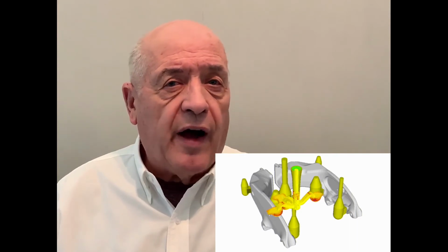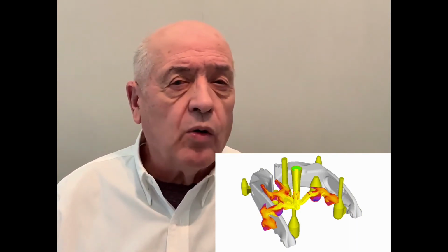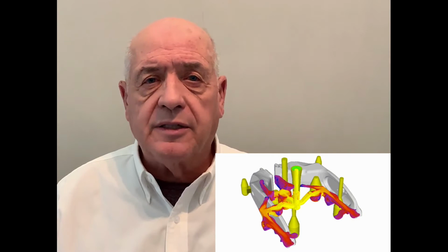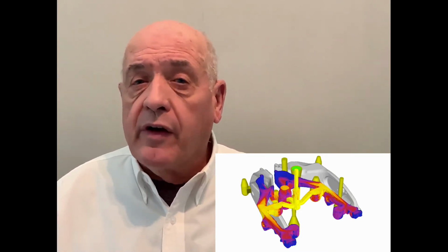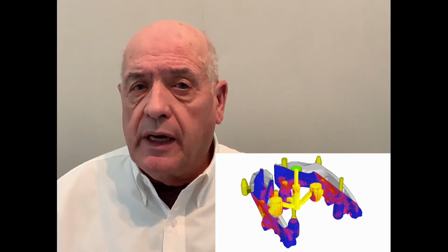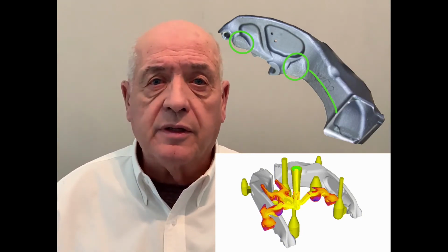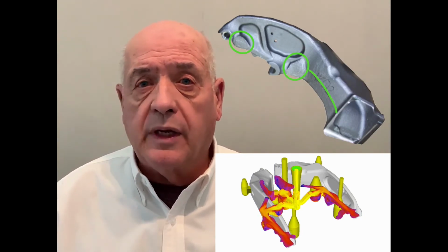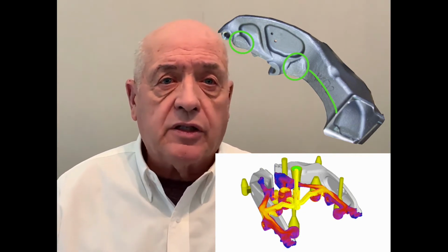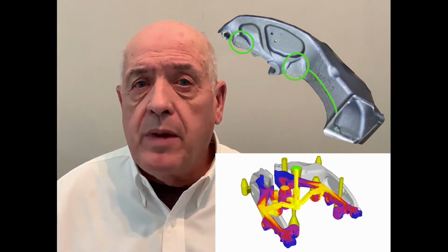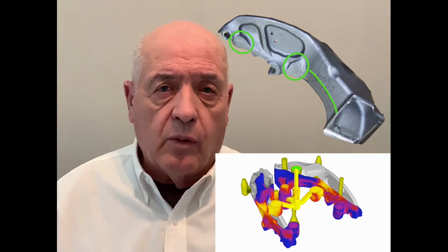The surface profiles of castings, depending on the mold cavity making process and the mold cavity tooling design, can vary considerably. Not only vary in dimensional capability from one dimension to another, but also vary in surface smoothness depending on what was connected to a surface in the process of filling the mold cavity and enabling solidification integrity to meet specified mechanical properties.